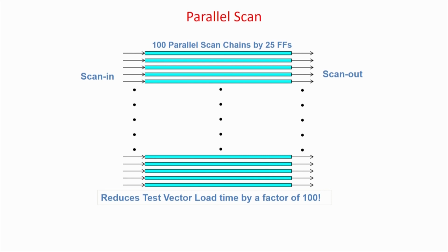That is one way of optimizing the scan chain, which is very popular, is partial scan. Select a set of flip flops which are easy to control, and don't make them scan enabled. Select another set of flip flops which are very difficult to control or cyclic, and make them scan enabled. So there should be a trade-off. The trade-off means we are saving in the number of pins as well as the ATPG computation time. So this trade-off actually is an optimization criteria.